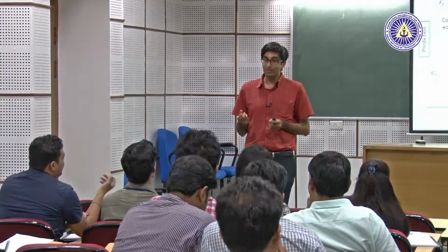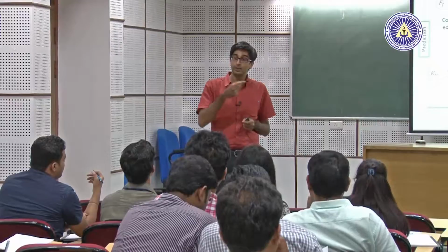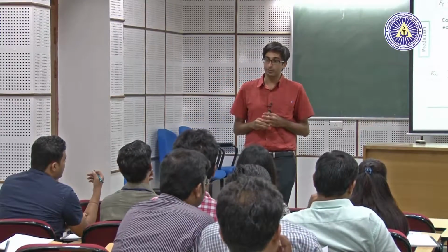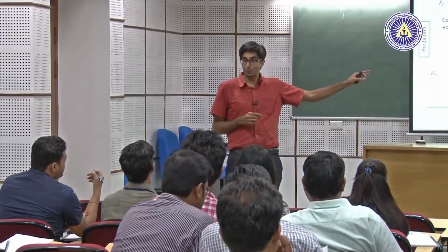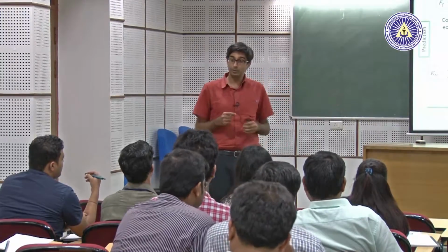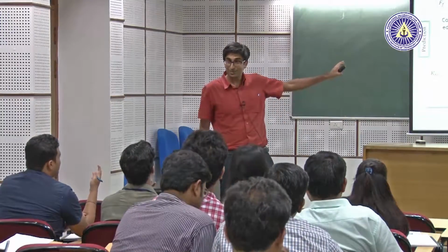Yeah, so my point is exactly this. If you want to really identify these coefficients, do them under the cutting conditions that are real for your application, because they will change. You do them in turning, they'll be different. You do them in boring because the boring tool is different geometry, it will be different again. This is a function of tool geometry.